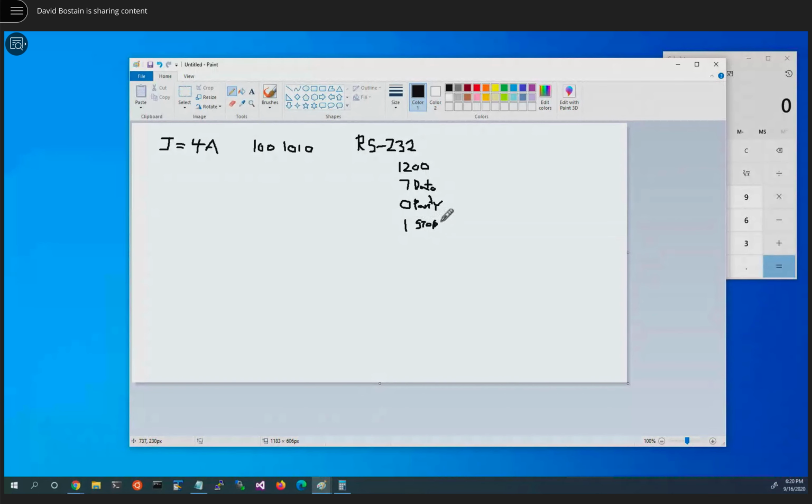Now let's assume for a second that they were going to do this. Well, if this had parity, remember the parity bit would be right here. So to compute it, we actually have to send the bits in that order. And we have to receive them in that order so that we know by the time we get here how to compute what the parity bit should be. Remember, we're receiving these bits in a serial order. We're not getting them all at once and then looking at the thing. We're just getting bit after bit after bit, and we have to know how to deal with that.